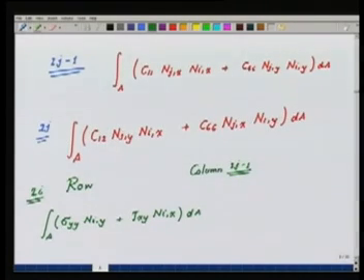okay, so this will have integral over the area of C. If I go back to the material matrix for sigma yy, it is C12 into Exx. So C12 nj,x ni,y, okay, plus C66 nj,y ni,x integrated over the area.